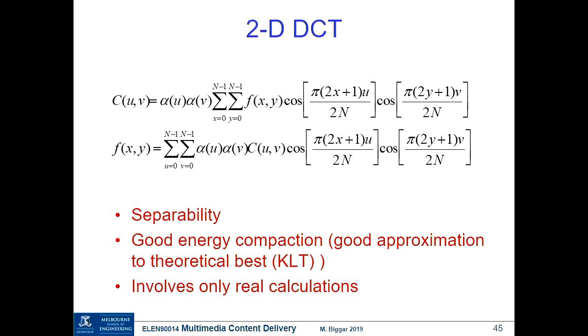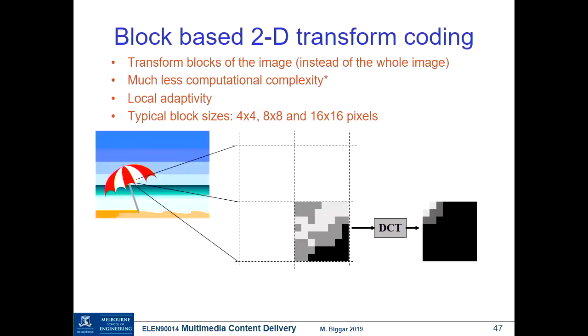But the effect is to do this. This is a bit graphical, but anyway, when we chop the picture up into segments, like 8 by 8 pixels, we transform each, and it has this effect that it decorrelates the signal. You can't guess one value by knowing another, and it concentrates the energy up into the low frequency coefficients.